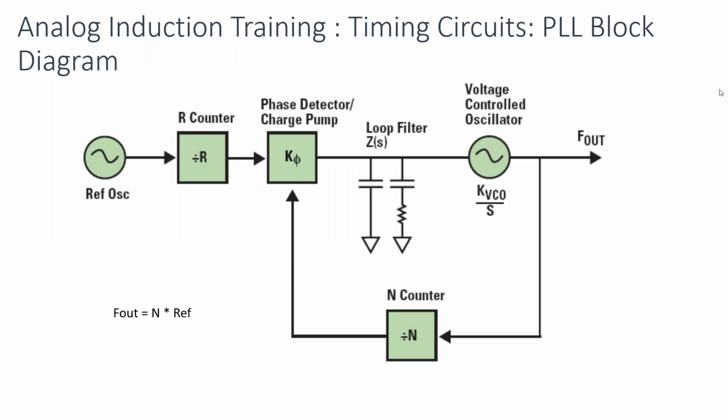So this is a typical block diagram of a PLL block. If you just ignore, particularly right now, the poles and zeros and other frequency elements and the stability issue, you can show that the output clock is n times the reference clock if I divide the input by n. So by changing n, you can generate multiple frequencies. That's the basic idea.